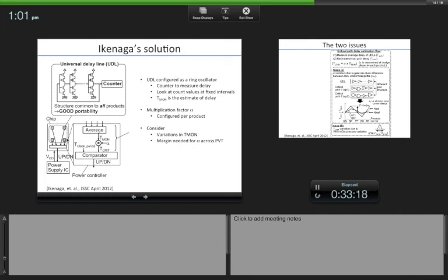Now these delay rings are placed at multiple points in the chip so that you average the readings from all the different points. Because you have a certain chip, and there is a certain variation of the process across the chip, what is called within-die variability. So the critical path on this corner of the chip, if you were to put it here, the delay will be a little different. The same critical path on this side will be a little different, and so on. That is because within the chip itself there are some variations.